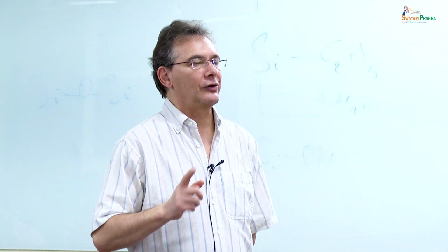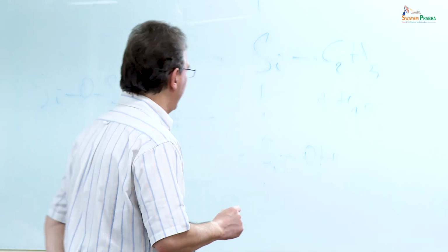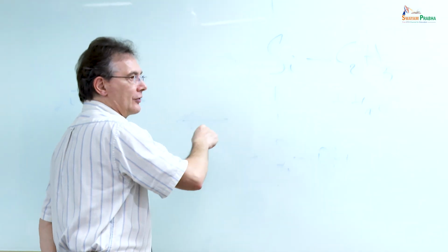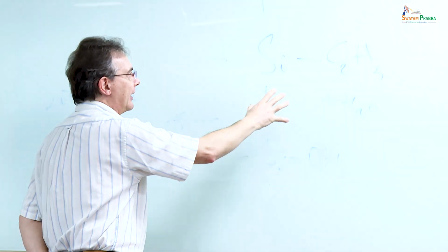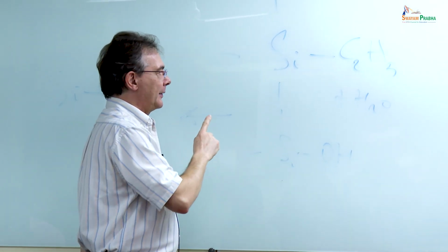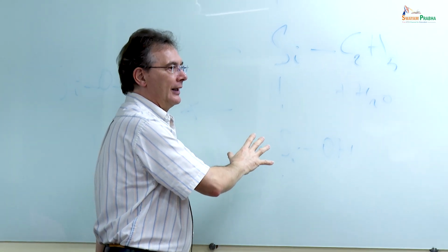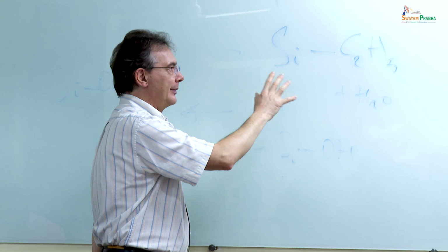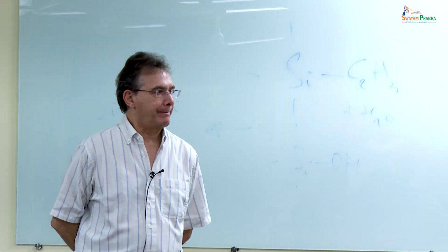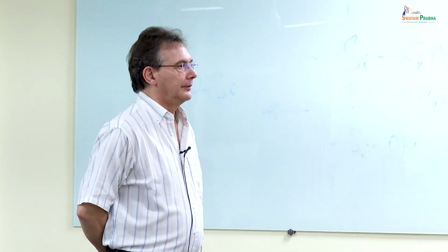Okay, so in the sol gel system, you need to add enough water to generate a fully hydrolyzed precursor. Otherwise, you will still have unreacted precursor. And we added, if I remember correctly, half of the stoichiometric water in the system because the other water was coming from the environment. So you're more or less using a single source precursor. So it's kind of stable.